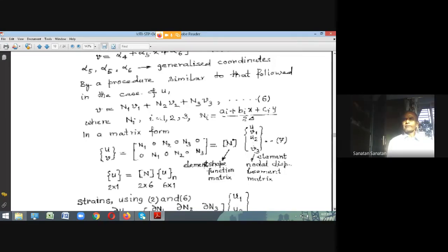But you see, stress-based finite element formulation is difficult, and it is not easily understood because the physics will be lost. What we have here is called displacement-based finite element formulation, an approximation based on the displacement form of the surface. And if it is stress-based formulation, then it is going to be stress approximation, which is much more difficult to understand. That's why that is difficult. And we'll come to that.